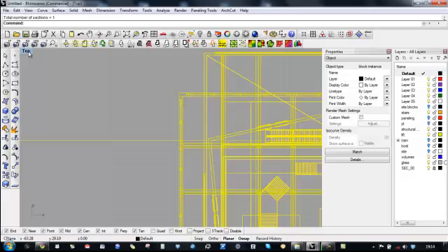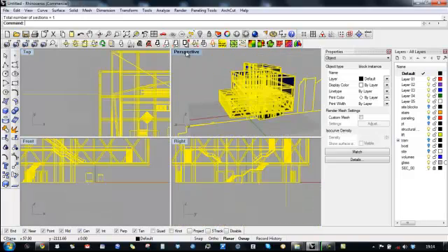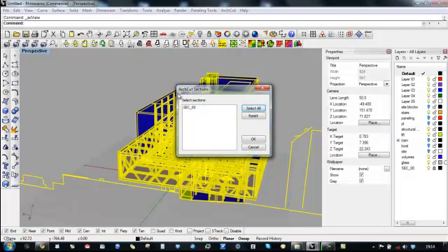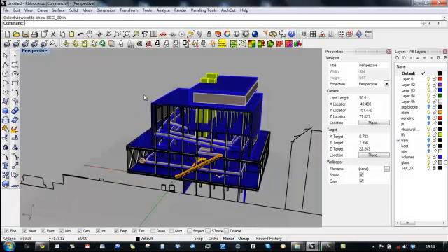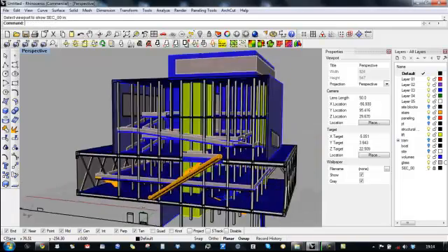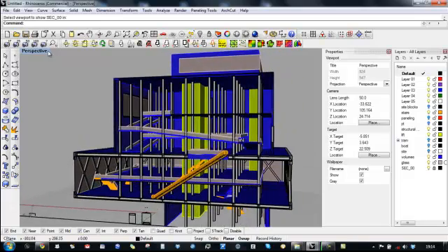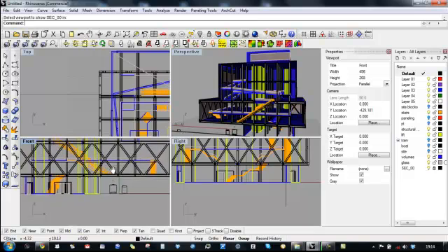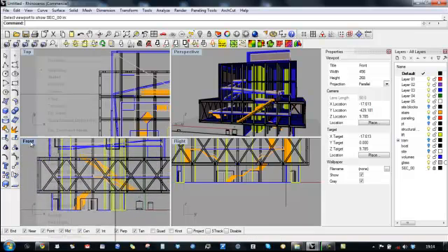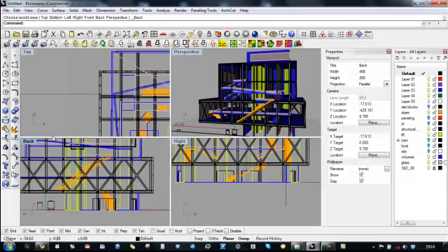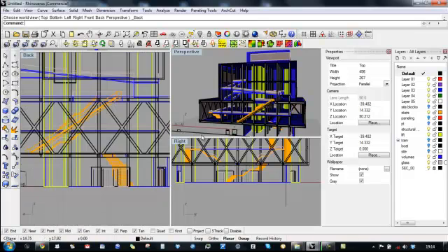We're just gonna go to the perspective, and we're gonna click this button, view section, select this section, okay, click in the viewport, and that's our section. Now, since I cut this section at the back of the model, I'm gonna convert the front view to back view. I'm gonna maximize this view and maximize the perspective,